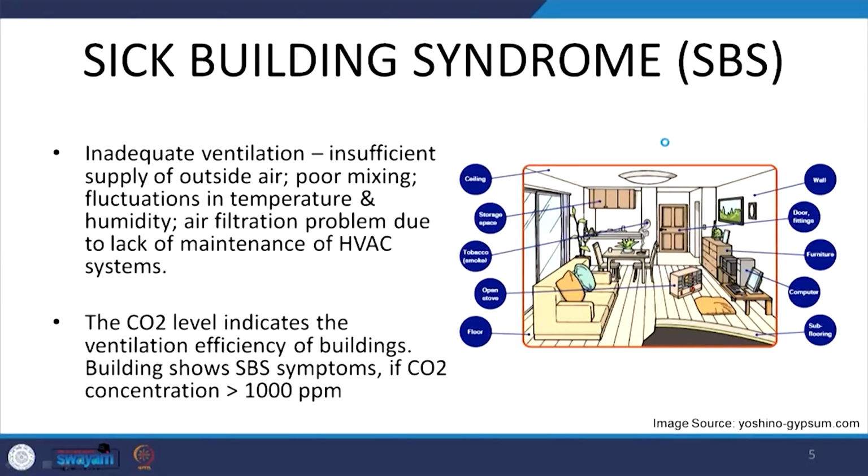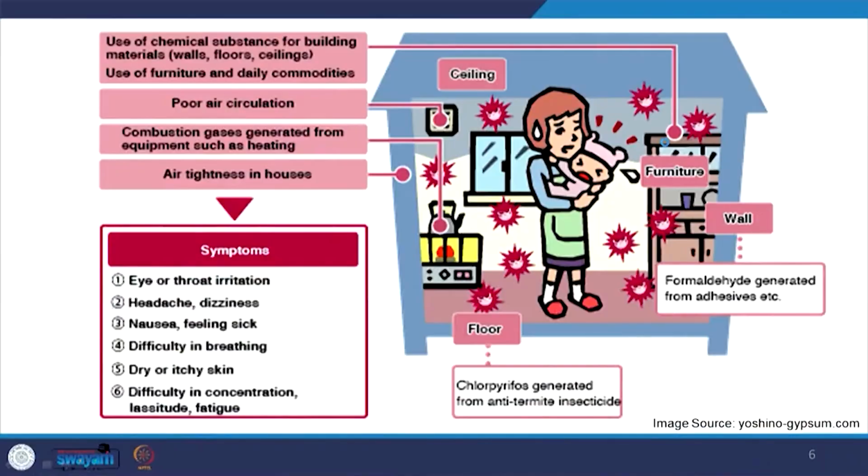Another very important reason for sick building syndrome is a very high carbon dioxide level. If there is inadequate ventilation, the carbon dioxide content would rise inside the buildings, the concentration would increase much beyond the standard, to larger than 1000 parts per million (ppm) of carbon dioxide. The more carbon dioxide, the greater the chances of illnesses experienced by occupants.